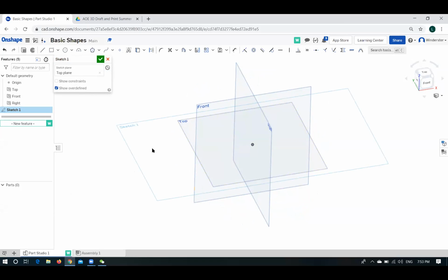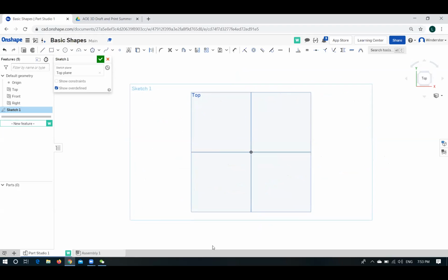Okay? You right click on that plane. It says view normal to sketch plane. Got that? So this will get you into a 2D drawing space. So you can see things that's no longer askew. Everybody got there?